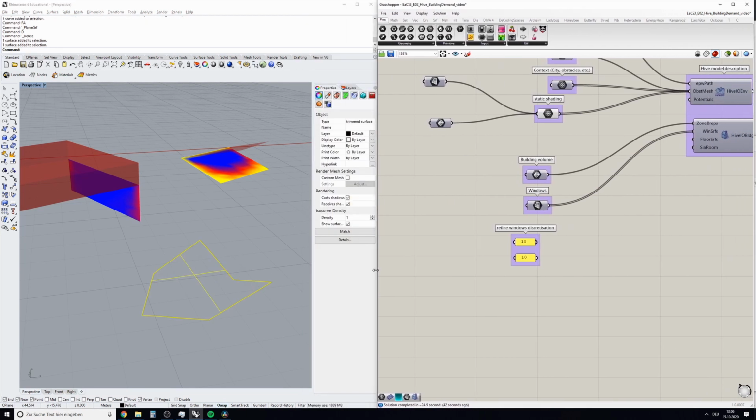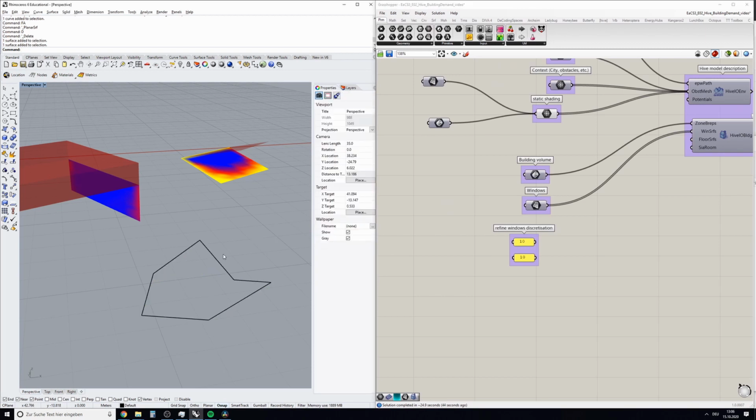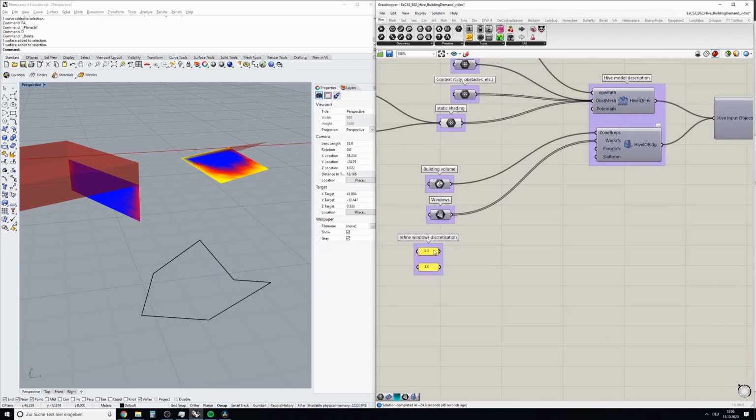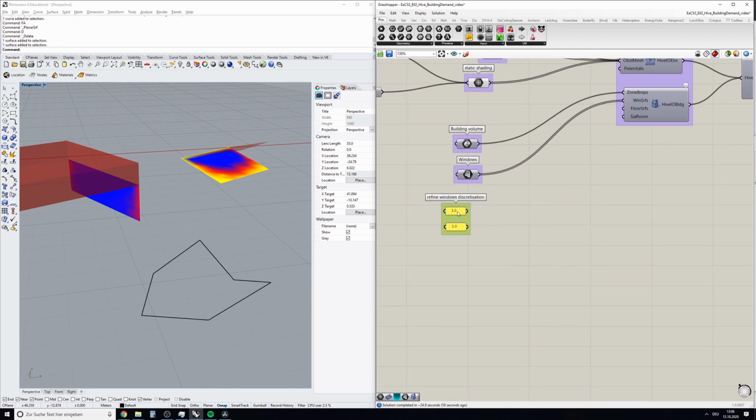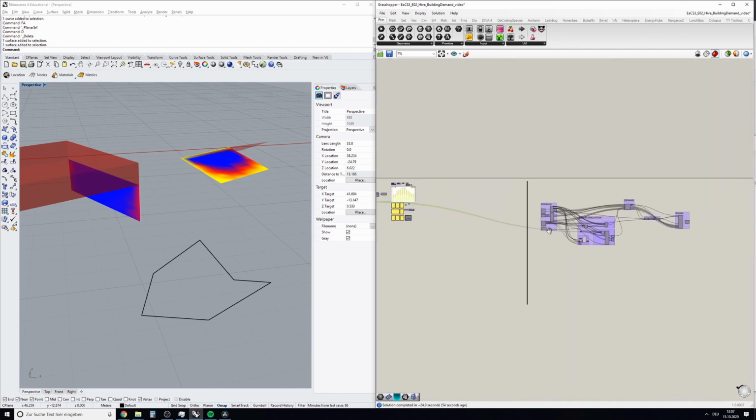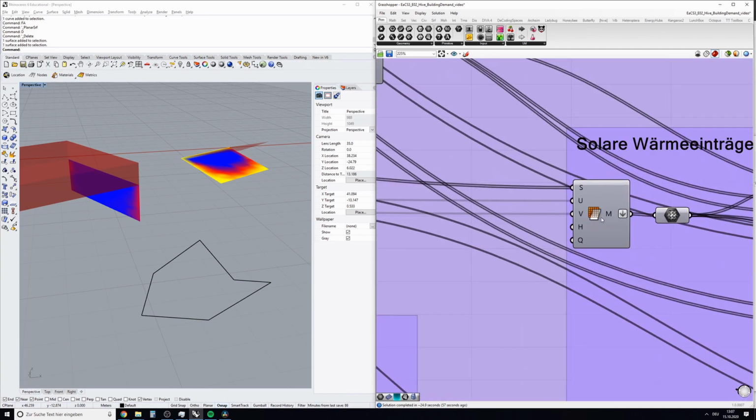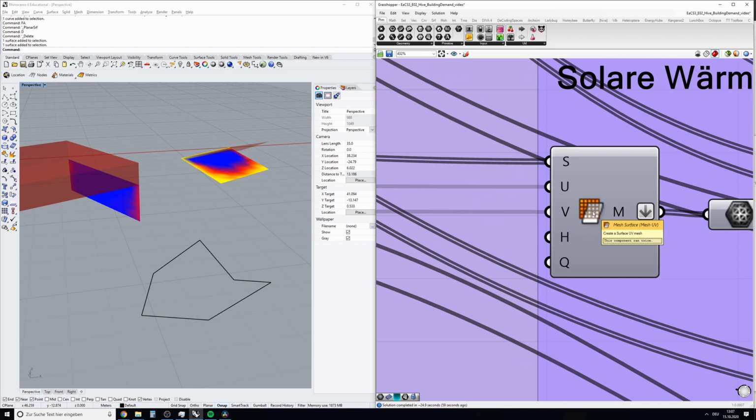Currently the meshing that is happening is done with the native Grasshopper component. If you click on these parameters, you will find where that connects to, this U and V direction discretization, and it goes over here, and that's really just a simple mesh surface component that takes a surface, takes U and V, and turns that into a mesh.